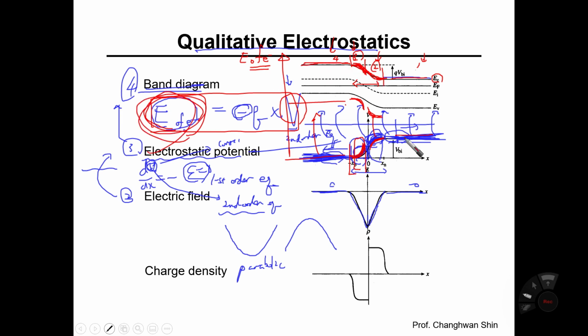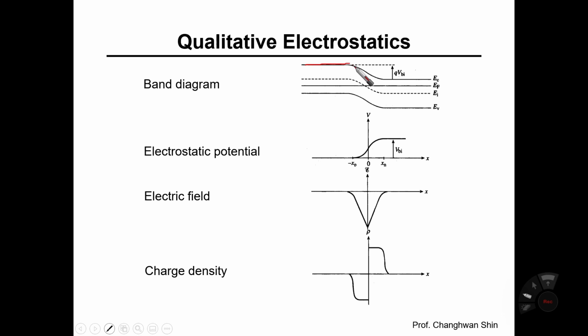So again, I'd like to say that this is a straight line. That is another straight line. However, here is corresponding to x of 0. That means a physical interface or physical contact between P and N. And the depletion approximation has been adopted. So at minus xp and at plus xn, the depletion layer has been limited in between minus xp and plus xn.